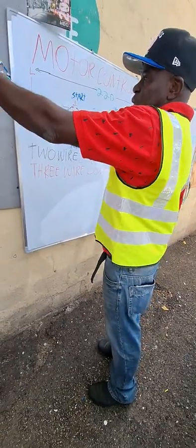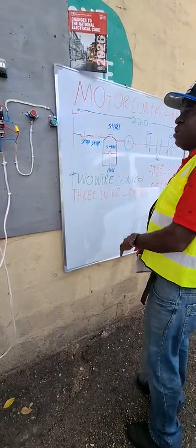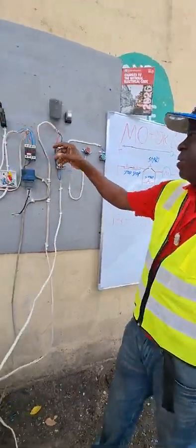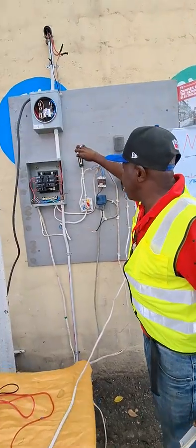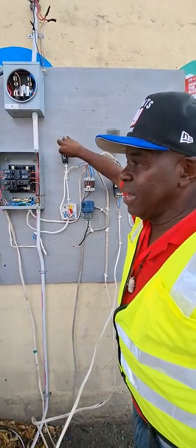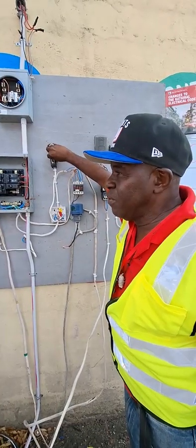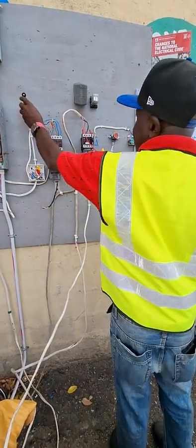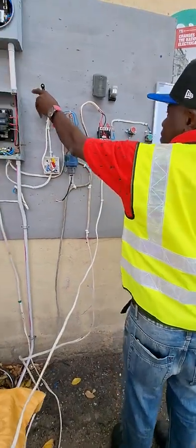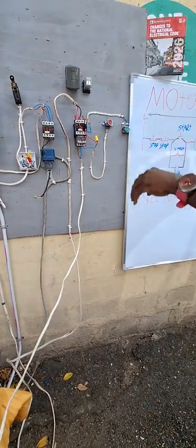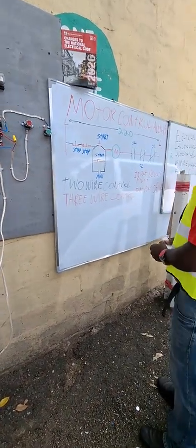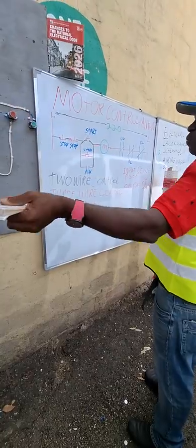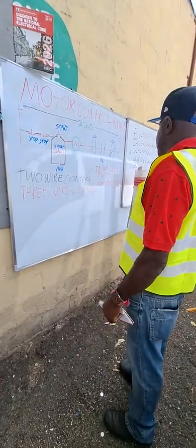However, with the two-wire control, that's not the case, because two-wire control is normally made for motors which are unattended, like water systems and certain process control. You have some motors that operate based on timing and so forth, so they pose no restraint to any operator.